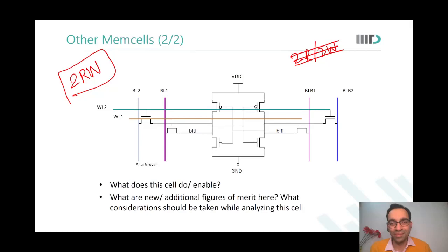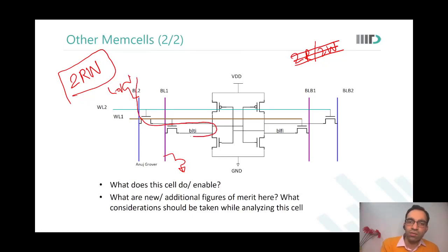Both word line 1 and word line 2 are on with different values of BLs. Yes. So we are saying that from one port, I'm simply keeping the precharge on. Okay, the precharge is on, but word line 2 is on, and on the other port I want to write. So what happens? Over here, there is a precharge that continuously supplies charge, which has to be sunk through the write driver. Till now, you were only designing the write driver to discharge this node. Now your write driver has to sink this additional charge continuously. Are you able to see this?